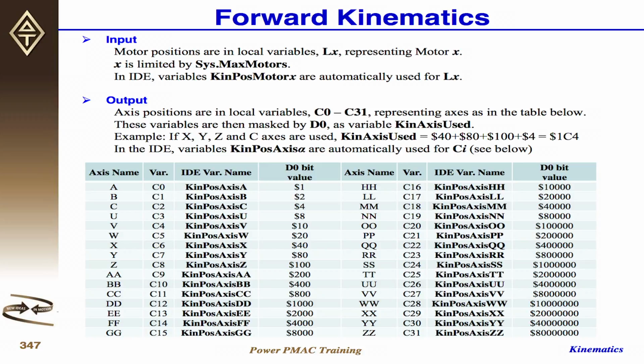The condition for stopping the calling of the forward kinematics is under these conditions. One is the home complete status bit, meaning if you want to execute your forward kinematics, I have to make sure that you already homed all the motors. Otherwise, whatever is in the motor position count, I will consider that's the correct position that got referenced. If you have a robot, then you have to define your 0 position, right?